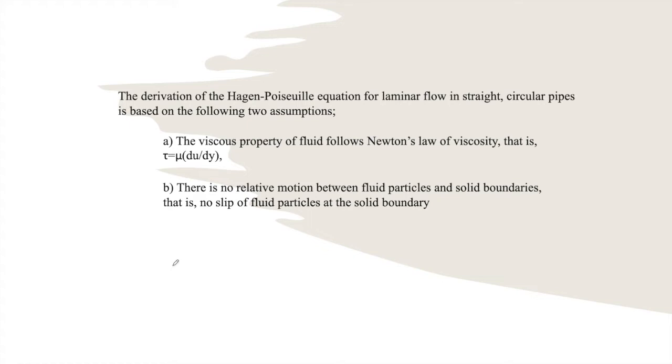So for Newtonian fluids, you can use Hagen-Poiseuille. The rest, the non-Newtonian fluids, for example pseudoplastic, Bingham fluid, rheopectic fluid, and many more, are not covered by Hagen-Poiseuille. You cannot apply the Hagen-Poiseuille equation to non-Newtonian fluids.